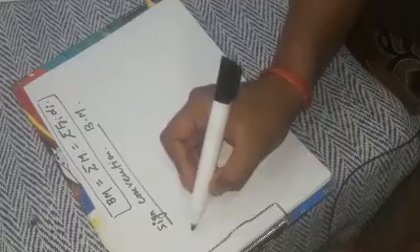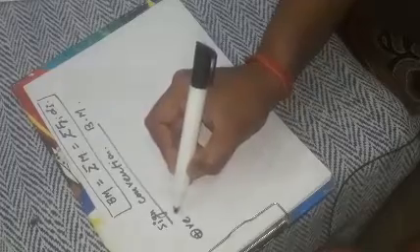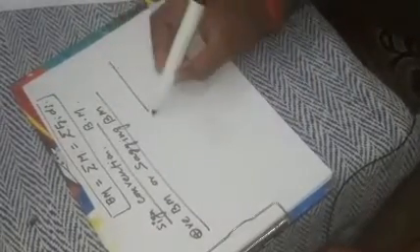So first of all, we will discuss positive bending moment or sagging bending moment. In case of sagging bending moment, this is beam AB, the beam bends in this way. The sagging bending moment always causes concavity in the upward direction, in the upper fiber of the beam.